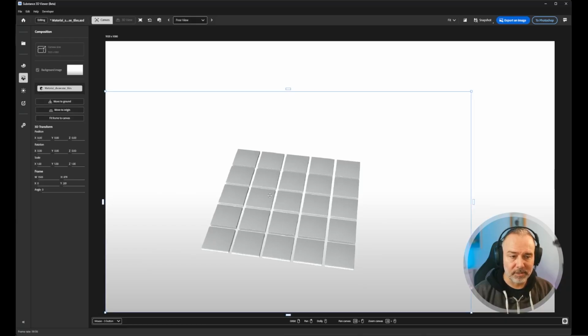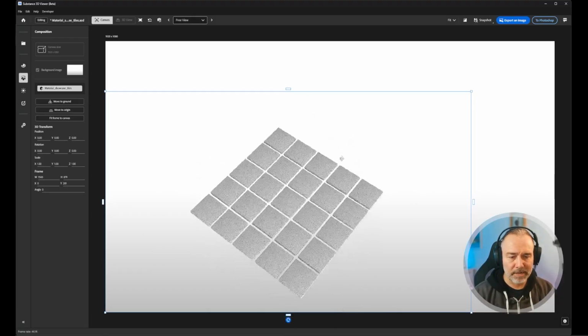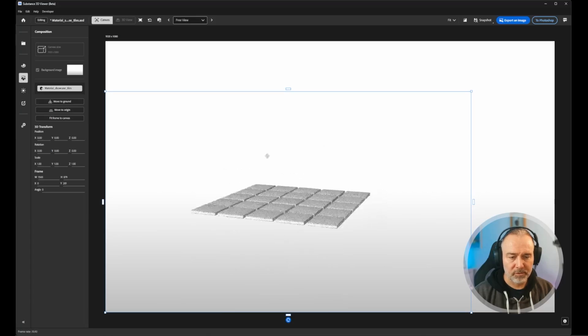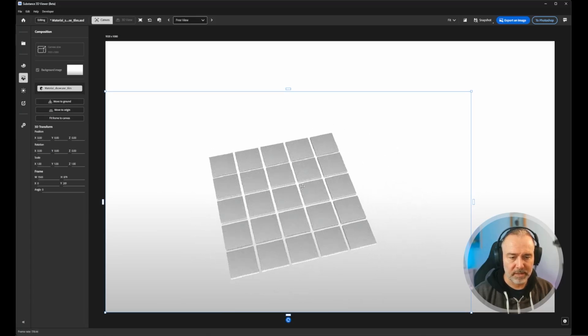But if I click on it, you see that you also see the frame, which is where the 3D object will be rendered. To manipulate it, I have a 3 mouse button, you have the control at the bottom if you want. On the 3 mouse button, right click allows me to orbit around my object, and middle click to pan it, and my mouse wheel allows me to zoom in, zoom out.